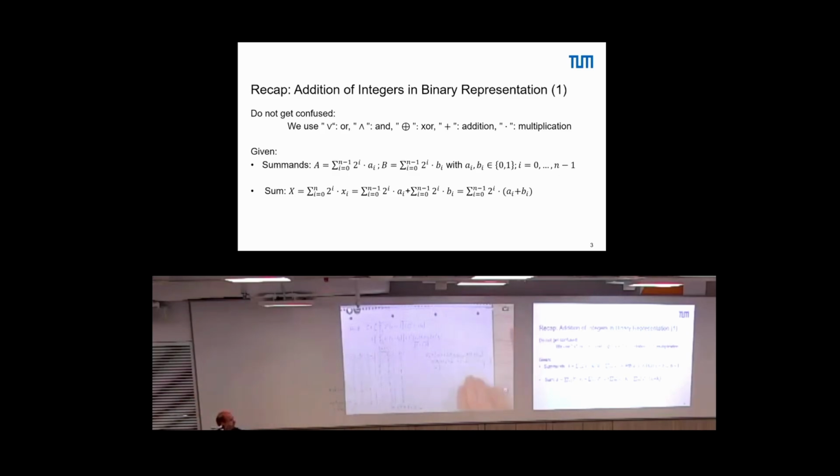Okay. Now back to this transform. Now I remove parts that are already covered, namely by AI and BI here, by this term. We cover already here the first term, right? So this here can only be 1 if this is already 1. And since there's an or in between, we can just remove this term, right? The same here. The first term can only be 1 if this one here is 1. So we can remove this term if we have the first one, right? So what we are left